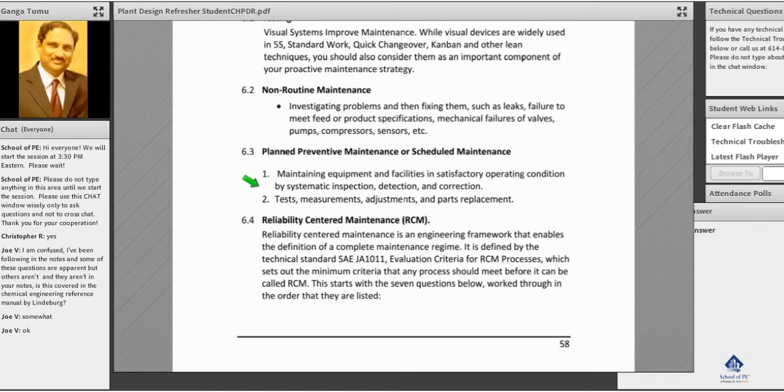They also check the tests and measurements. Wherever there is instrumentation, they check whether the proper current is getting to the instrumentation to properly open and close the valves. They also check that all the actuators are working properly, and they fine tune and adjust the specifications of each piece of equipment and each sensor, and put it in place.